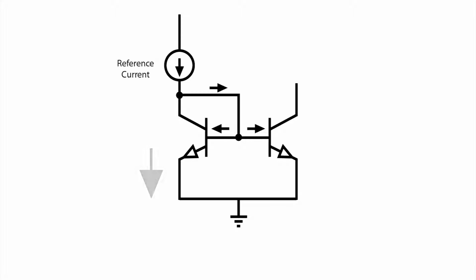So the reference transistor turns on and lets some current pass through. Remember that the sum of twice the base current and the collector current is equal to the reference current that we want mirrored. The base current acting on the second transistor allows an almost equal amount of current to flow through it. This is how the current is mirrored. Through this process, we can replicate the reference current at various points in the circuit. This is known as current steering.